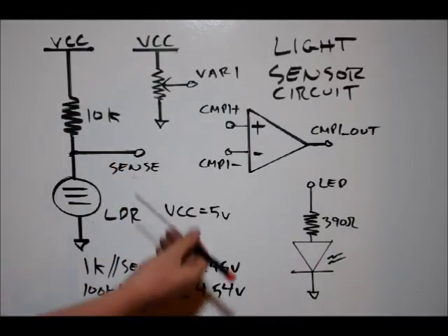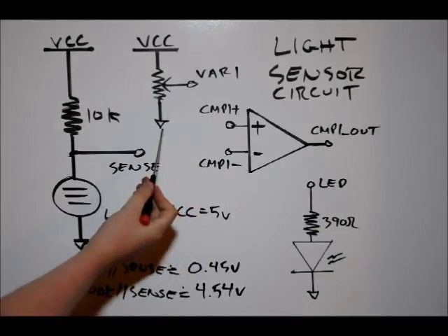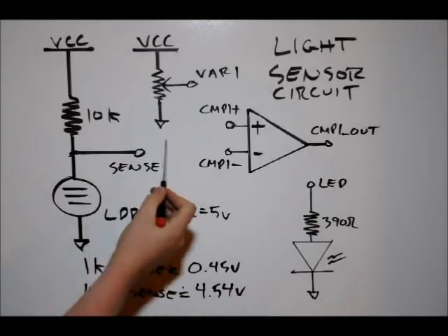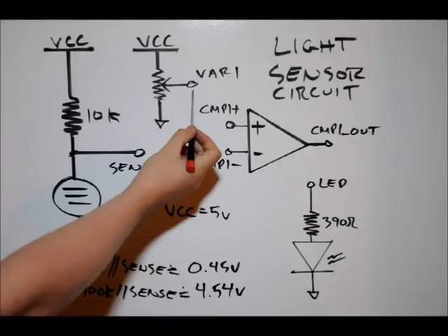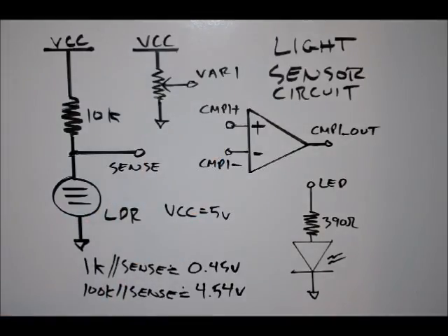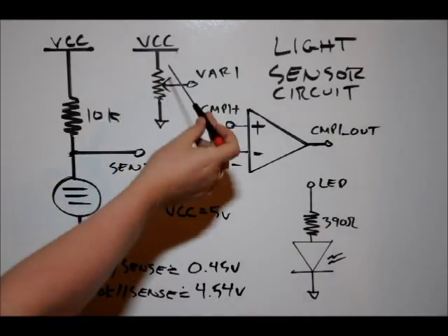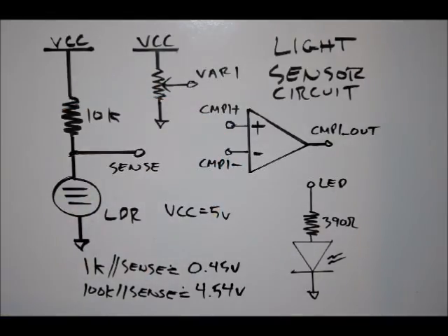What we have to do is take a multimeter, and connect our negative probe to ground. This is our ground reference point, meaning they are all interconnected. Then take our positive probe and place it on the wiper line, which is labeled VAR1 for variable resistor 1, and use the screwdriver to tune that output voltage to 2.5 volts.